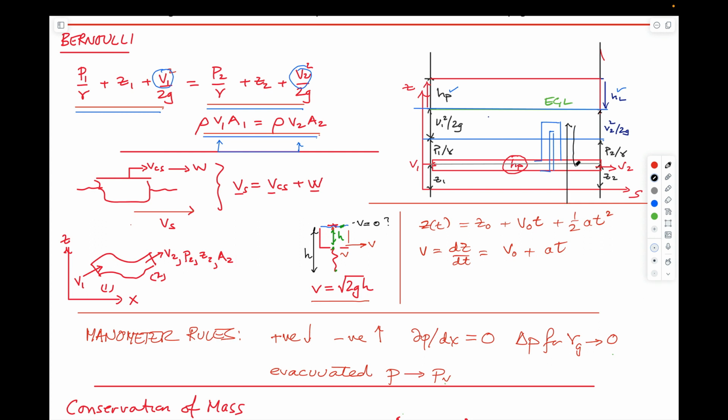This would be the pressure head of that point, if this is exiting at atmospheric. If it's not exiting at atmospheric, then we would go down to this point here. And then that would allow this component here to be the velocity squared term. So elevation, pressure, and velocity head. This has to be a sub-atmospheric magnitude of pressure, so this magnitude is lower than the magnitude here. So we need to be able to accommodate that.